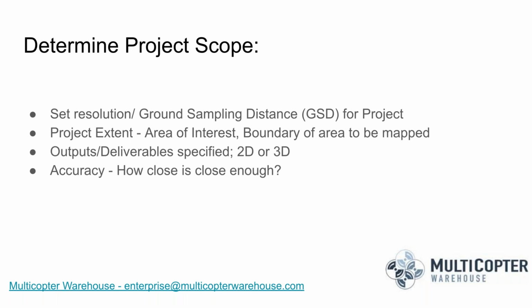That's a good question. Most of the time when you speak with a customer or a client, they'll say, oh, well, you can get 1 centimeter. That's what I want, the highest resolution possible. But to get that higher resolution data will require you to fly your UAV at a lower altitude, which could potentially put the UAV in, I don't want to say danger of horizontal or vertical obstacles that you might run into, but more specifically, it'll require you to capture more images to get the footprint of your project area, and ultimately require both more time in the field collecting the data and also more time processing the data, ending up with larger deliverables that maybe the customer doesn't really need.